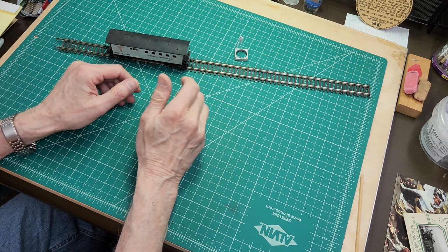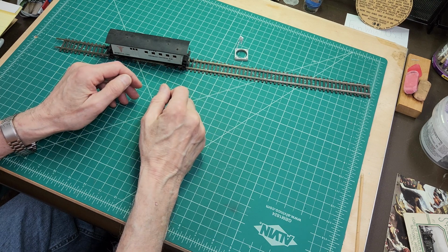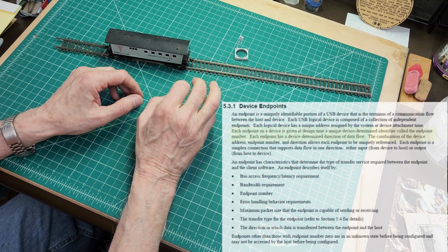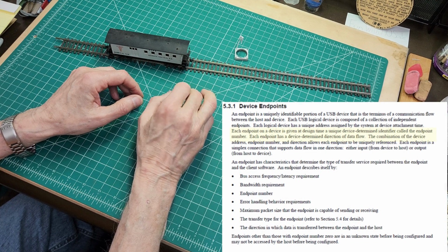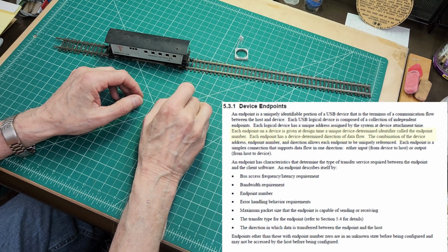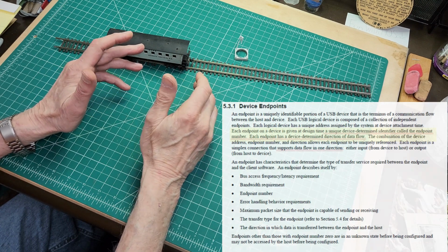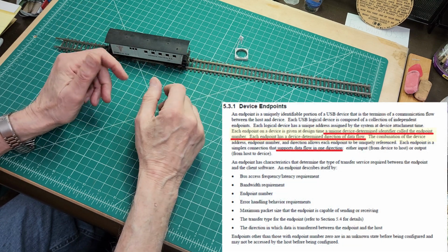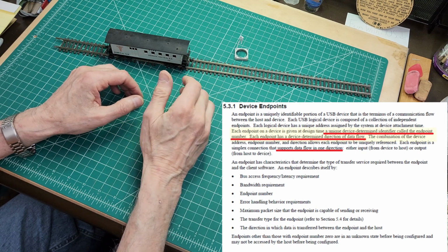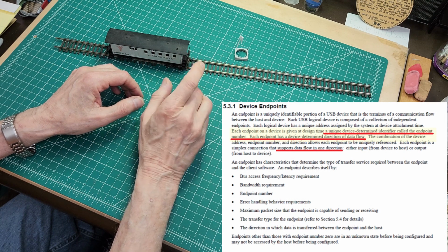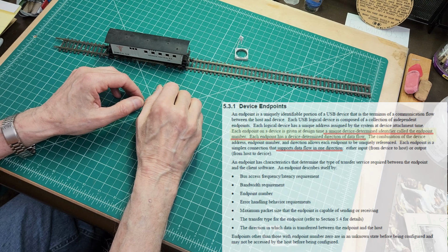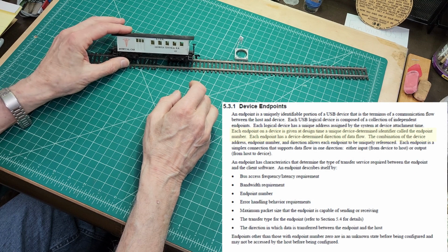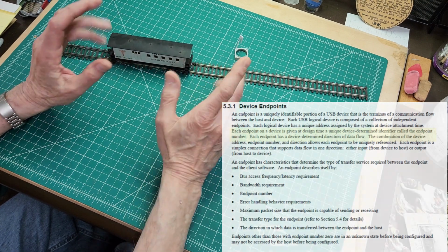One is an input and one is an output, as I said, and USB has an absolute rule. This is the specification I'm talking about, that only endpoint 0 is bidirectional. That would mean to me that endpoint 2 must be either an input or an output. But yet here it's from the NCE interface that port 2 is both. That just doesn't seem right. It's troubling.